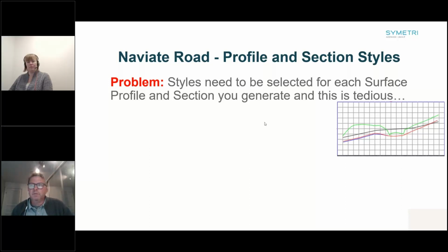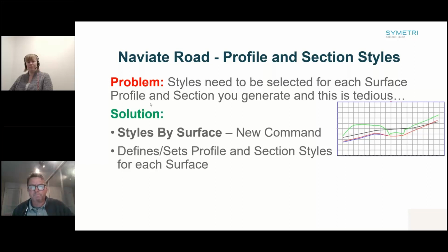So over to some juicy bits, and this one I also saw. Thomas, you're on the call. This is your request. Profile and section styles can be a tedious thing, because when you create profiles and sections, you need to set the style for each of the profiles and sections you generate. And especially when you use data shortcuts, you've got to set them up when you create new profiles, and which style should you use.